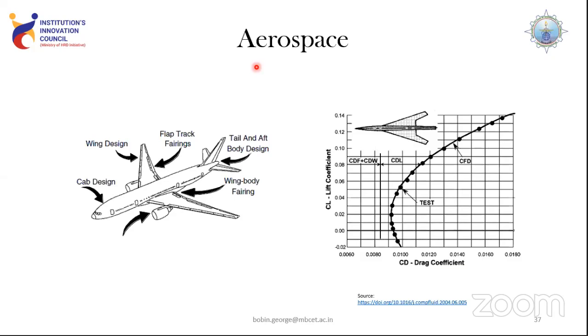We generate a computational domain, and with the help of tests that have already been done, we carry out the numerical analysis and see whether the two tests exactly match the previous case. That means you will be plotting the coefficient of lift, that is the amount of lift force generated for an object, and the drag coefficient, that is the opposing force acting upon that object. This is one of the ways. There are many other ways. Once that design is finalized, you can apply it onto varying geometries so that you can generate a much higher amount of results.